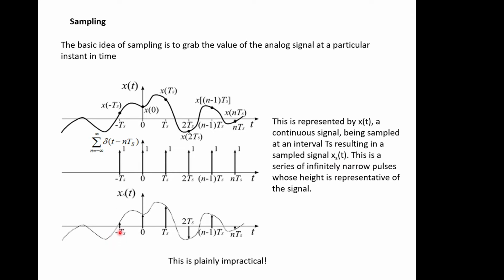So we've got xs of t here, which is these points taken at discrete points in the waveform. So we do that by sort of convolving it really with a time point, and we're sampling effectively mathematically with a set of points that are infinite, have an area of 1, and are infinitely thin. And then if we multiply these together, we end up with infinitely thin spikes that have the height of the original waveform.